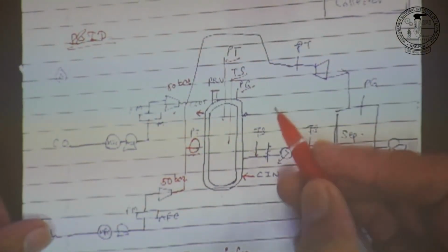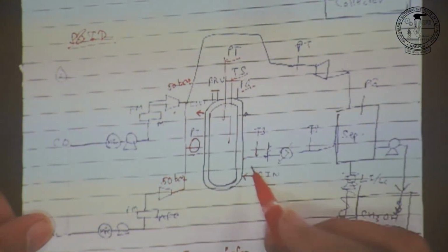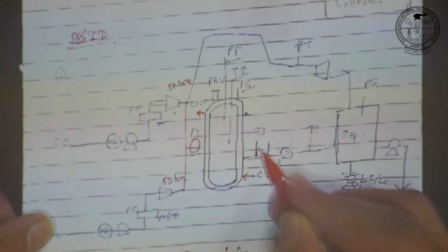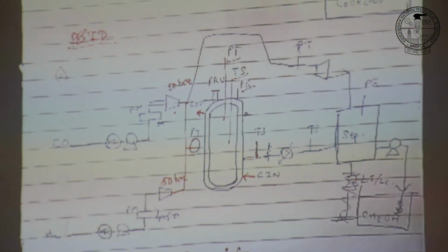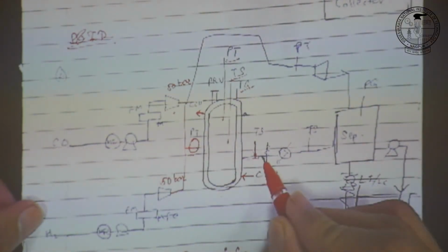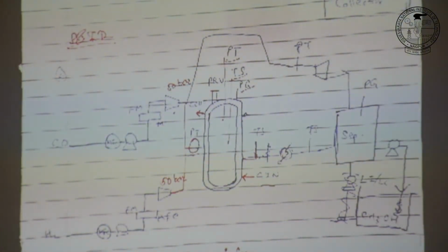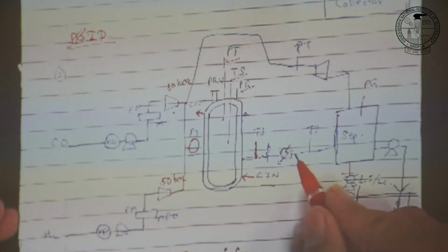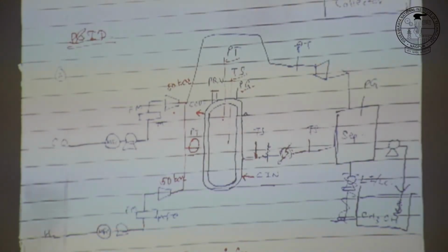Then after the reaction occurs, the outlet temperature of the reaction is measured. For that reason, a temperature sensor is given on the outlet stream of the reactor. After measuring the temperature, the heat exchanger is given, and the amount of water flow will be set so that it regulates the temperature as required. And after cooling down, again a temperature sensor is given to detect any changes in the temperature.